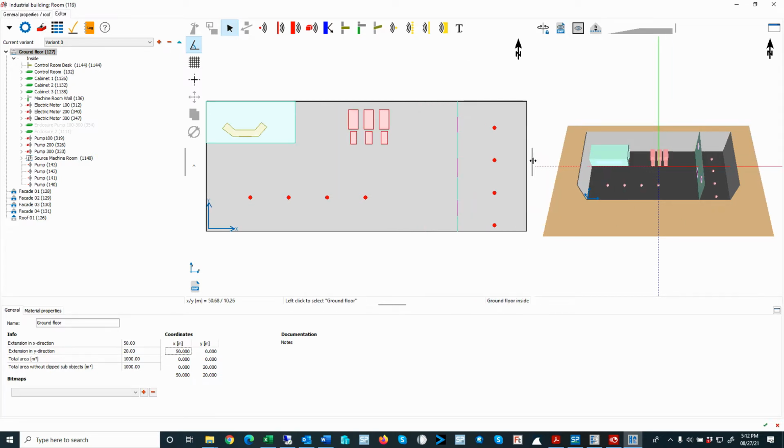All right. Up here at the top, we see the different objects from point, line, area source, machine, which is basically a box. And then we have absorption areas. We have horizontal and vertical objects and tilted objects. So that could be a tilted surface that you can define in terms of transmission or absorption. Then in terms of receivers, we have point receivers. We have a measurement path, cross-section receivers, or area receivers. And then you have geometry text. So that's for more documentation purposes.